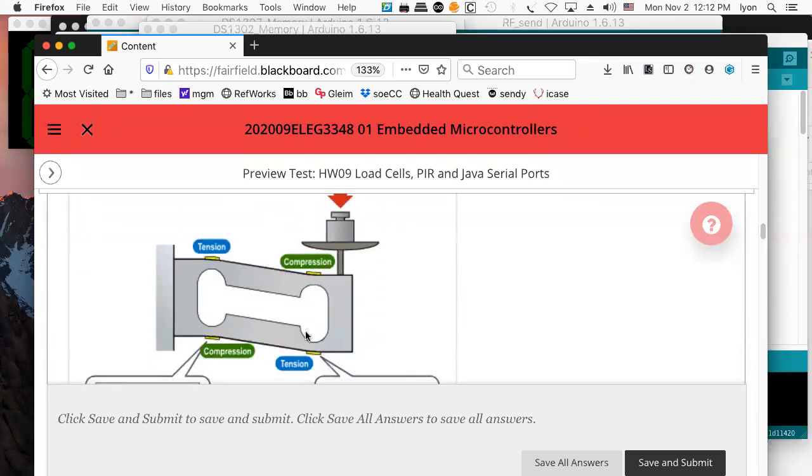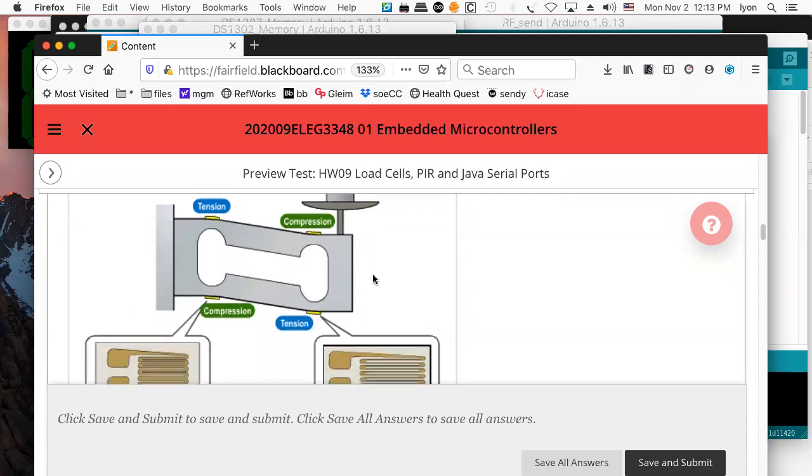So this is cool. Right now we're seeing sort of the schematic diagram of the load cell with a strain gauge here and here. This one's under tension. This one's under compression. That one's under compression. This one's under tension. And there's some load coming in from the right. The left-hand side is fixed to some sort of fixed frame of reference. That might be like the scale housing. And this might be the scale platen that has some flexure, goes up and down.